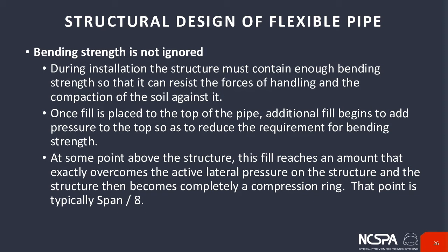But after you get the fill placed on top of, around, completely surrounding the structure and up to that minimum cover, after you get that amount of soil support around the structure, then it does start to act in ring compression, and the bending strength of the pipe at that point is generally inconsequential to its performance in the field.